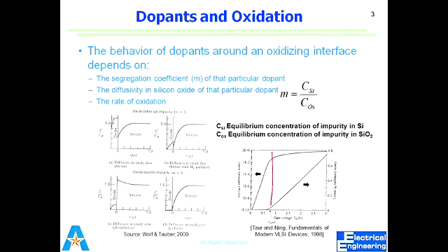We are growing the oxide, not depositing. I told you that we can deposit as well, but right now we are discussing growing, and for that we need a silicon substrate. This is the surface of silicon, and it will keep moving down as we grow more and more silicon dioxide.